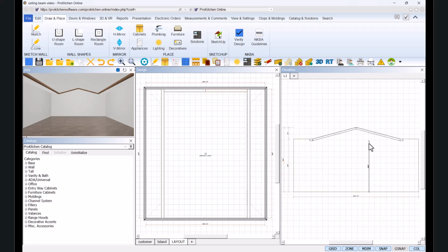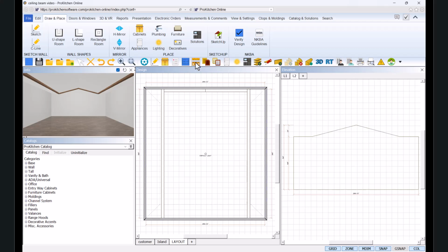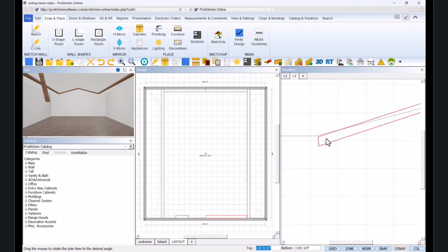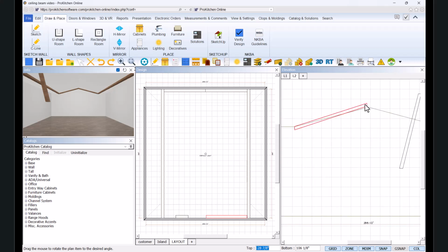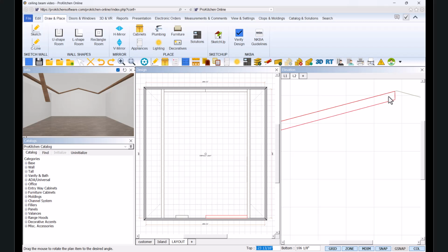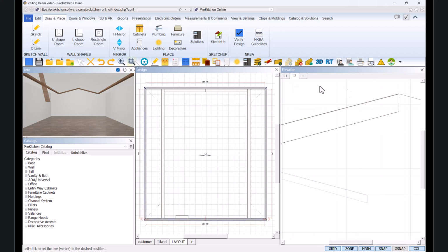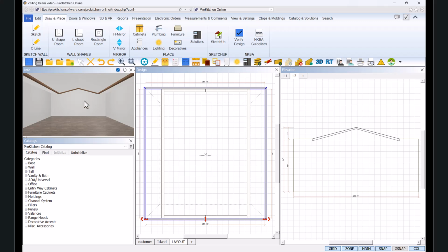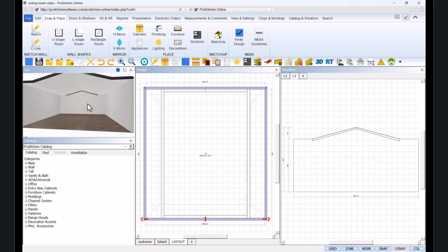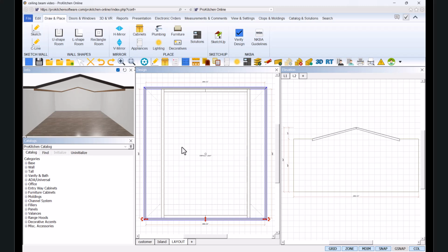Now we may open the elevation view of the south wall, so we may copy and paste the two beams we just created into place. And of course, make minor necessary adjustments of the rotation and mitered end edits to finish the angled ceiling beams at the south end of the room. Fantastic! Now we have angled ceiling beams at both the north and south ends of the room.